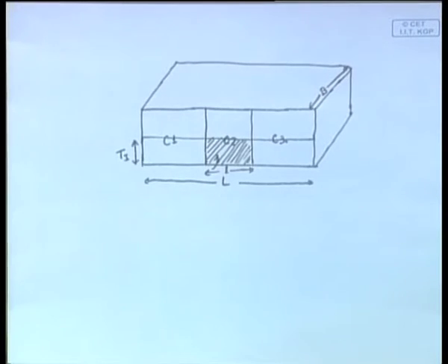That is one way of looking at it, which is the method of added weight. In the other method, the method of lost buoyancy, you have the weight of the ship as such, but some buoyancy is lost. Remember, even after it has lost its buoyancy, the ship still has to finally come to a state of stable equilibrium where the weight is equal to the buoyancy.